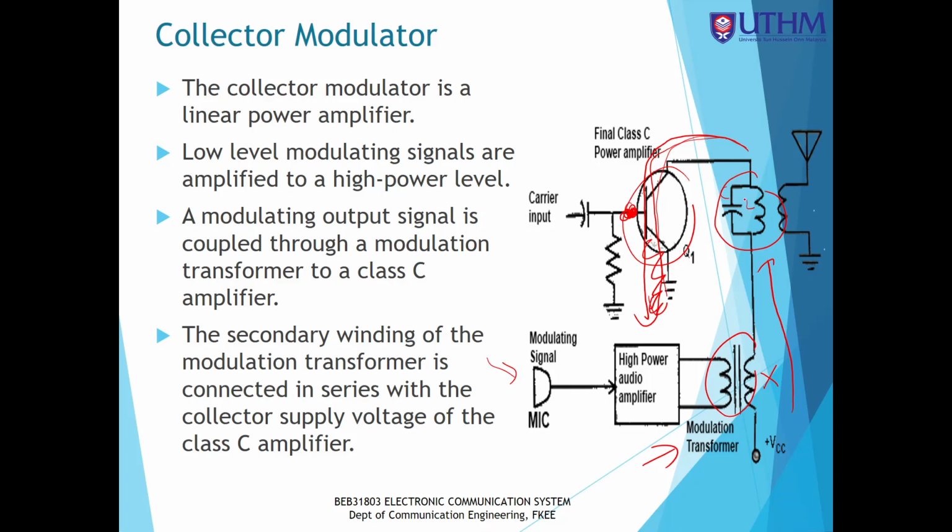At that point, the LC tank circuit will discharge, it will resonate and produce the other half of the negative cycle of the AM signal. So this charging and discharge process, resonate and non-resonate process, will produce a complete output AM signal, positive and negative side.